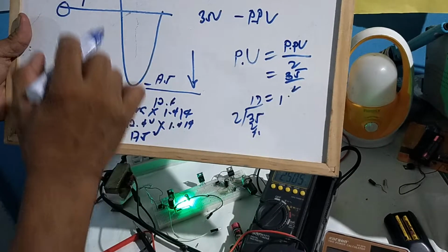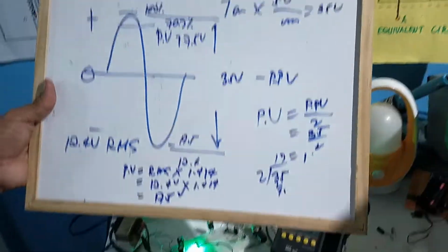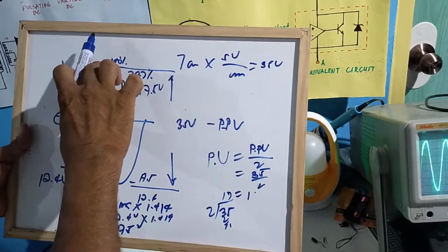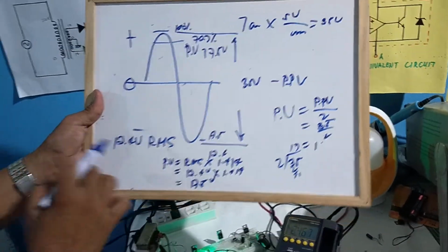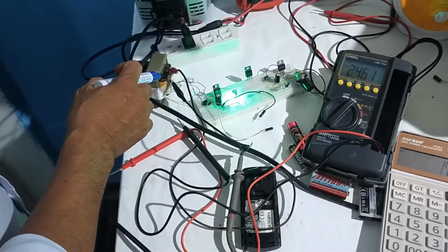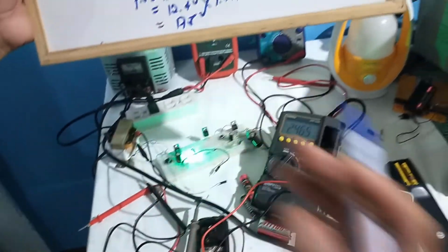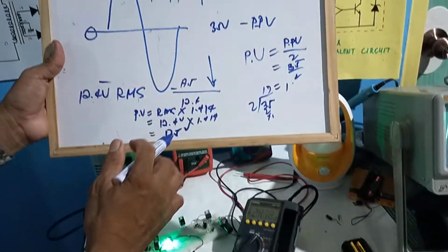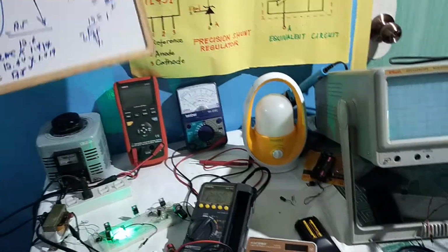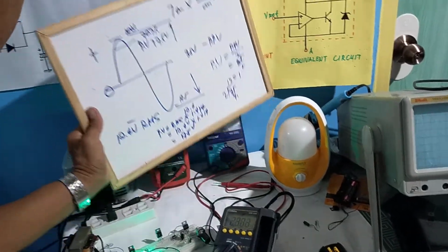So we are right, because the peak value here based on the oscilloscope is 17.5, half of the cycle. And this 12.4 volts is the measured voltage here, the effective value, measurable by our multitester. And it is exactly correct, 17.5. Okay, it goes like that, class.